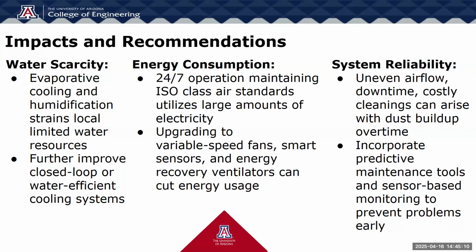Lastly, to maintain system reliability, we suggest sensor-based monitoring to detect early signs of airflow disruption or filter clogging. This predictive maintenance approach helps prevent costly downtime and keeps performance consistent. Overall, the proposed model of Exhibit D, especially with these enhancements, offers a balance between cleanroom performance, operational efficiency, and sustainability.